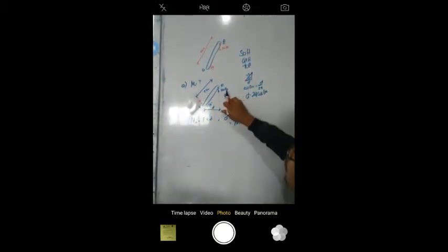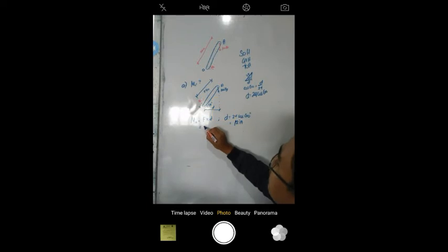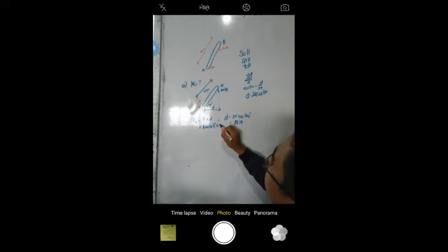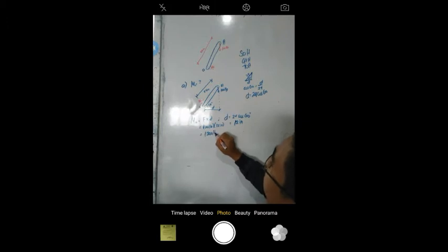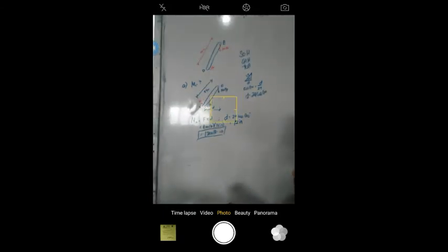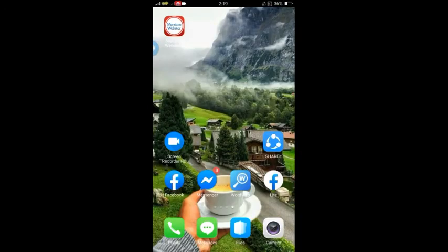So yung distance ng force na ito, with respect sa point O is 12 inches. So force natin is 100 pounds times 12 inches. So yung value natin is 1,200 pound-inches. Okay? Yan yung value ng problem letter A natin. Let's proceed sa B. Ano daw yung horizontal force applied at A which creates the same moment about O? So ano daw yung value ng horizontal force?